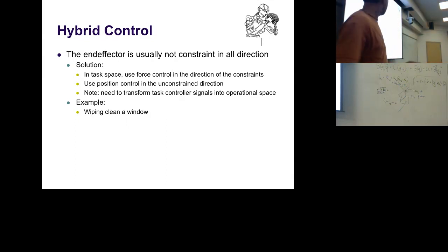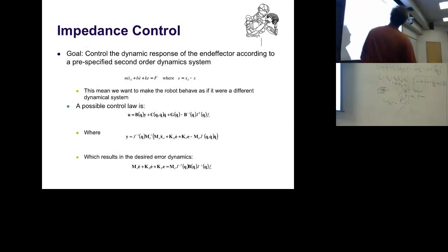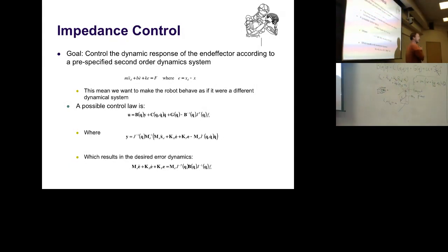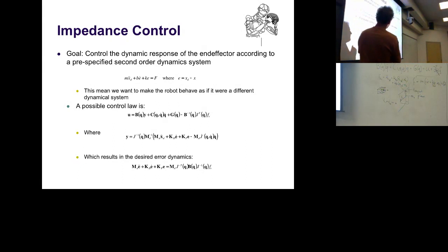Now, last but not least, and this is just mentioning it, you can go into the entire story now and do impedance control. This is when you don't just care about the force, but also the force due to stiffness. We only considered KE here, remember? But you could now also start considering forces which come through viscosity or through inertial forces. And then the control laws just become more complicated. I'm not going to go through them since it's too annoying. You can look in the book.